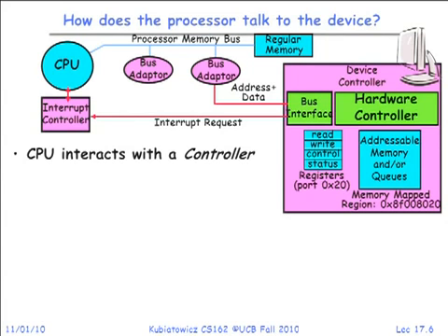By reading and writing these registers, you put it into different modes, like use VGA mode, or use really high density graphics mode with automatic rendering. You can do that with a bunch of control registers. Any device you look into is going to have some combination of control registers and memory.